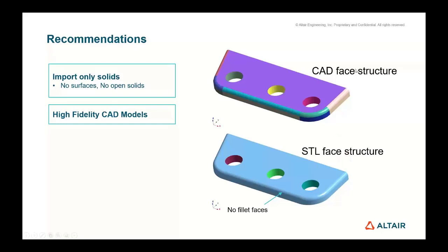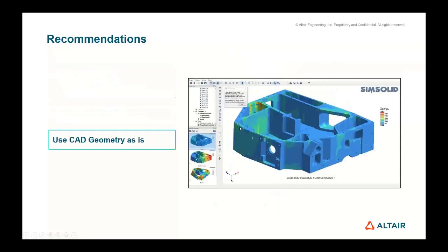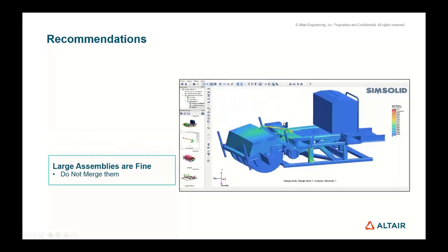And just so you know, you can work with CAD as well as STL, so any scan data that you have, but just be careful because obviously with scan data, it will assume all of it as one surface. So just make sure if you can bring CAD in, just bring your CAD in if you can. Use your CAD geometry as is. So where you have pinholes and everything, don't feel like you have to remove them.